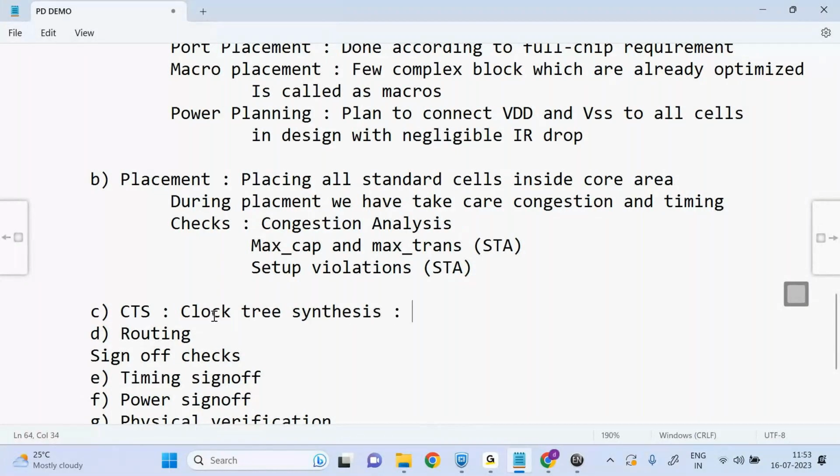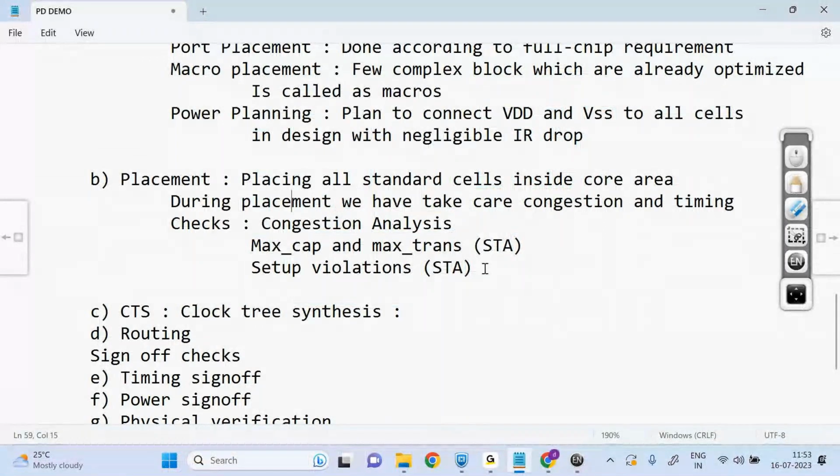There are some other checks I think we have, used after placement. Yes, I think legality issues and unplaced cells checks. Unplaced cells also we have to check after the placement. Yes, legality is not a bigger issue. Legalized placement will fix the legality issues. Only if you have very low utilization will you run into legality issues. That is not a bigger issue, even though it is also one of the checks. We have plenty of checks, but these are the major checks we have to do.